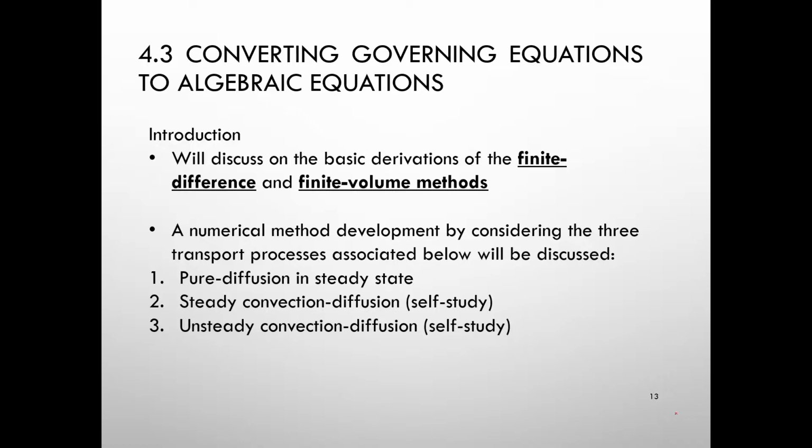So we continue our lecture with 4.3, which is on how to convert governing equations to algebraic equations in order to do these numerical simulations. So in this chapter, basically we are going to discuss the basic derivations of the FDM, the finite difference method, and FVM, finite volume methods. Next, we are going to consider appropriate applications of these discretization techniques to solve governing partial differential equations numerically.